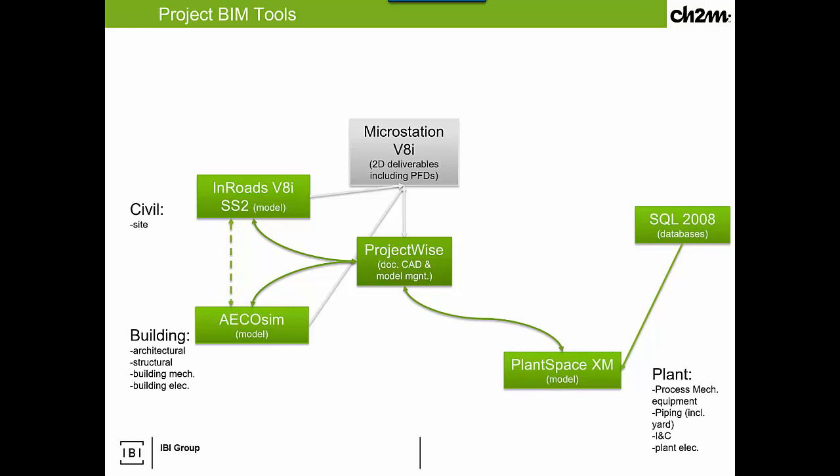Plant modeling is the type where, in the example I used, I can't make a 2-meter diameter copper pipe because the material doesn't do that, nor can I do a 1/2-inch reinforced concrete pipe because that would just be foolish. So the SQL database has all the rules and mechanisms upon which I can then build my piping model. So it ensures the quality and consistency of that information when I'm in the model environment.